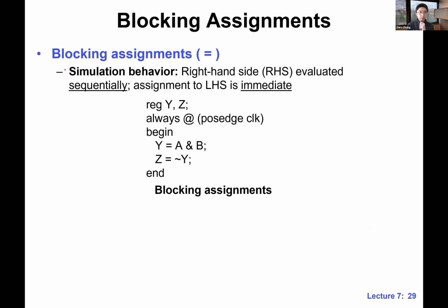All right, so coming to blocking assignment. This is one of the more confusing concepts, blocking versus non-blocking. With blocking assignment, we are using the equal sign. It only matters when we have multiple statements in an always block.